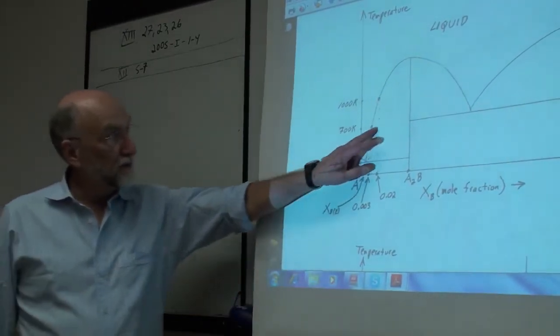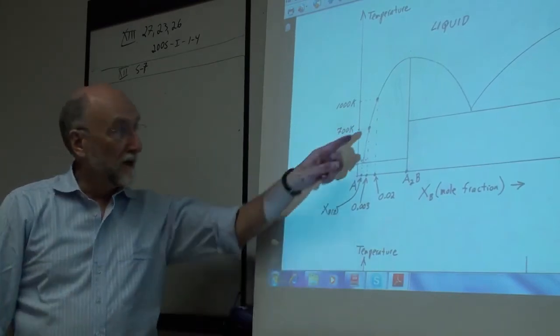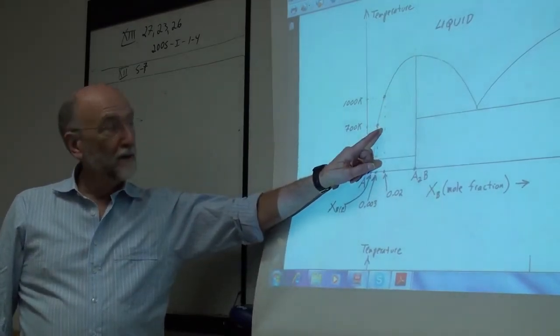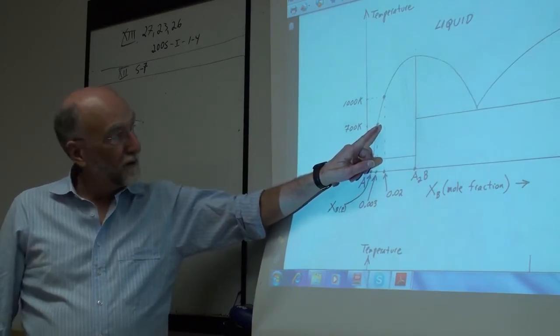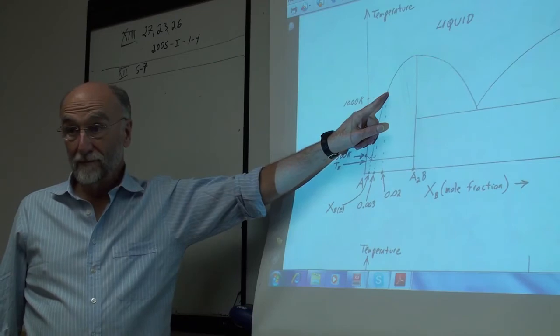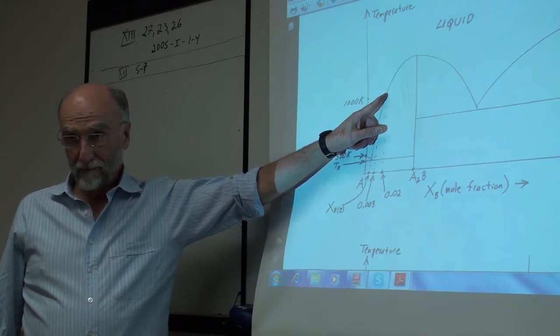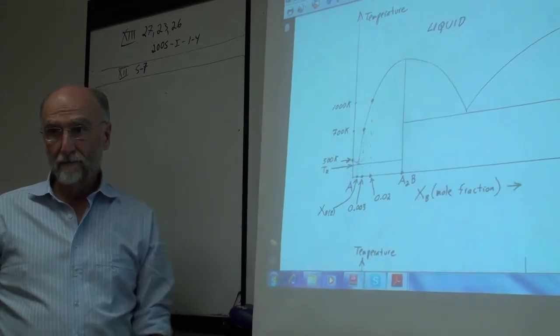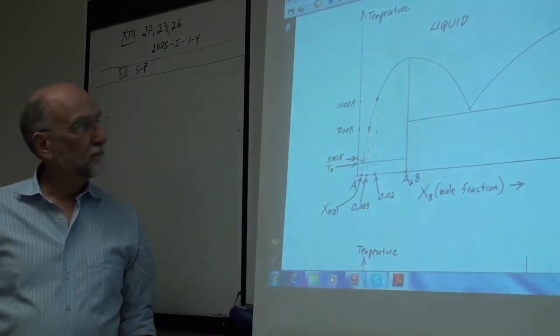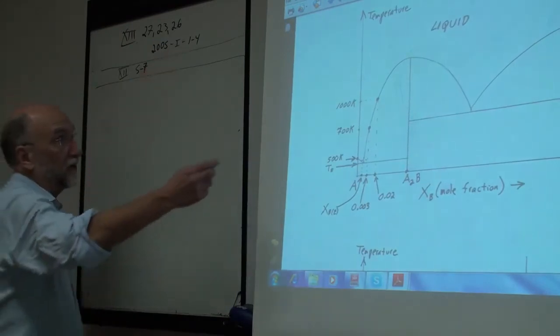I calculated the activity, well, in the first part of the question, those activity coefficients I calculated are the activity of B solid at those 2 points. Yeah, I mean RT ln a_B in liquid minus RT ln a_B in solid equals minus delta G fusion of B, which is also applying in this liquid. No, no, this is the liquidus of A2B. So along this liquidus,